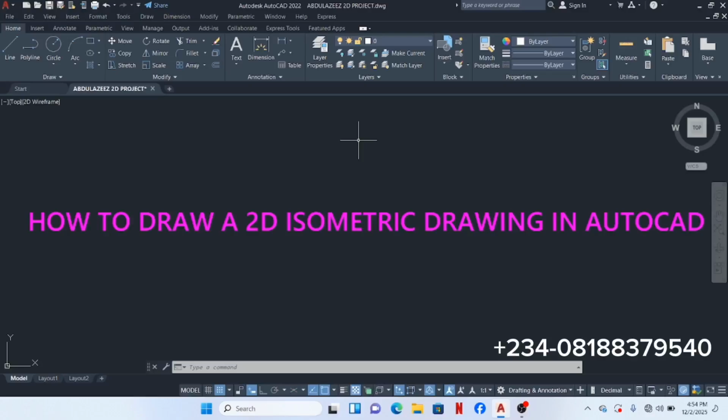A 2D isometric drawing is a flat representation of a 3D isometric projection. That is, it is used to provide a faster way of creating an isometric view of a simple design. Distances measured along an isometric axis are correct to scale, but because you are drawing in 2D, you cannot expect it to extract other 3D distances, the areas, display objects from other viewpoints, or remove hidden lines automatically.